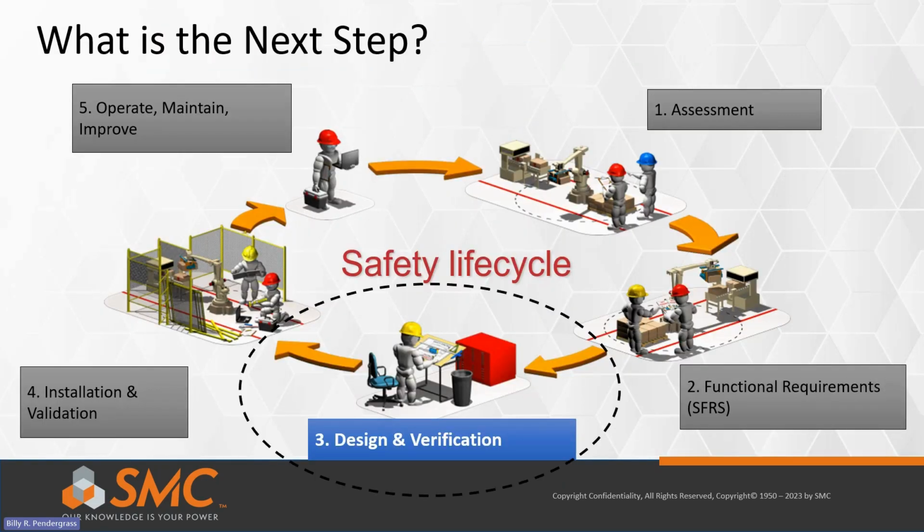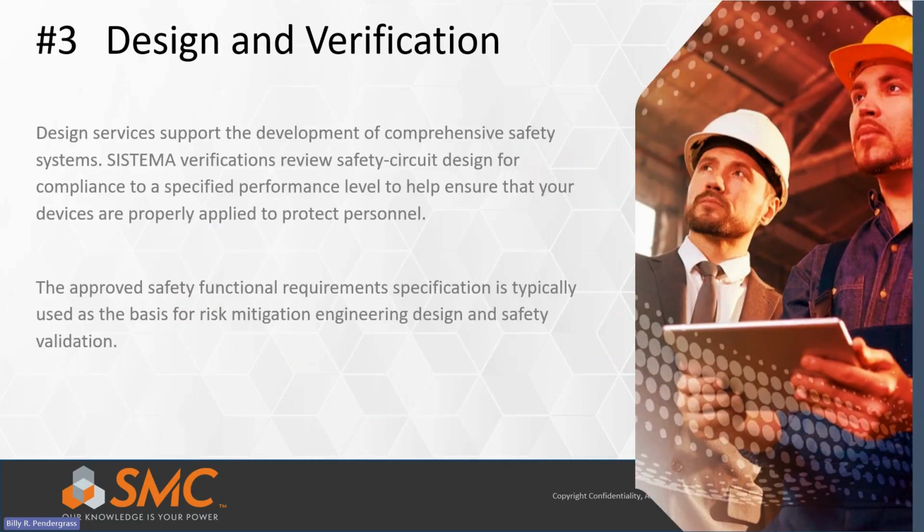You guessed it, after the approval of the SFRSs, we design the safety function. Using the SFRSs as the basis of design, we engineer to a specified performance level to help ensure everything is applied appropriately to protect personnel. Using SISTEMA, we now design the appropriate safety systems and review the design for compliance to a specified performance level to ensure that your machine is properly equipped to protect personnel.